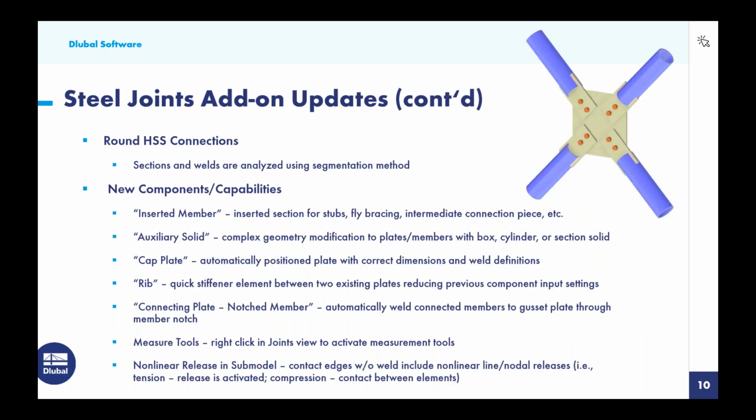We also can now consider round HSS connections. Previously, this was a small limitation that we had. So these sections and welds are analyzed using the segmentation method, and we'll take advantage of this connection today in the upper right-hand corner with these round HSS members.